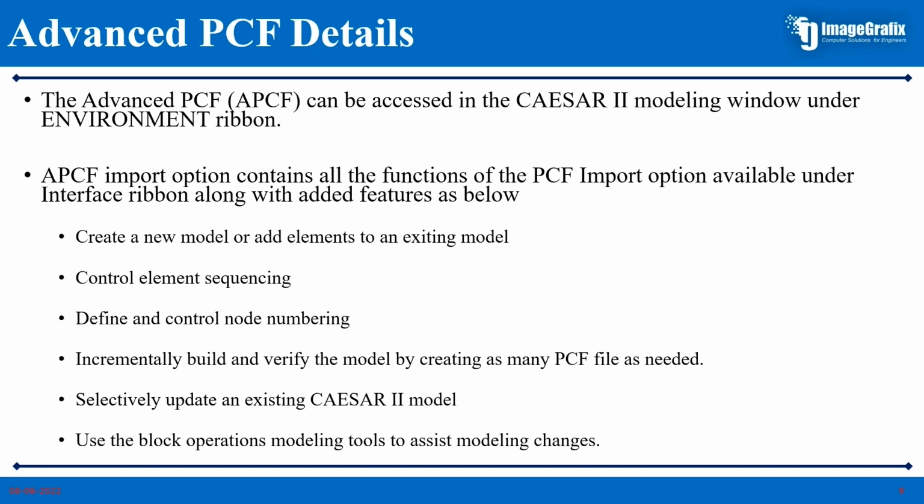These things we can do. We can control element sequencing, so if you want any block sequencing to be created, we can control it over here. Or you can even define and control node numbering systems. You can very much do that. You can even increment your build and verify the model, creating as many PCF files as needed.